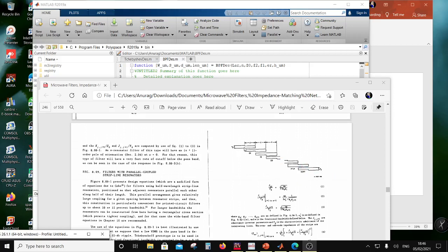What he will do is put in these lines with certain arbitrary widths and certain arbitrary spacings, and then put a goal on S11, S22 and S21 and try to run an optimizer. Well, that's a blind way of designing a filter and doesn't give you an idea how to implement it, because you do not have an idea of the structure of the filter and how it works or why it works. So you have to be a designer, you don't have to be an application engineer.